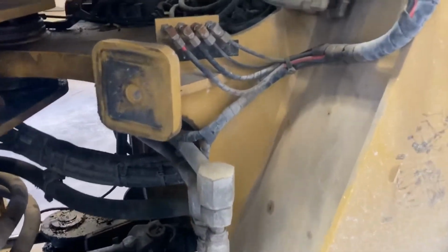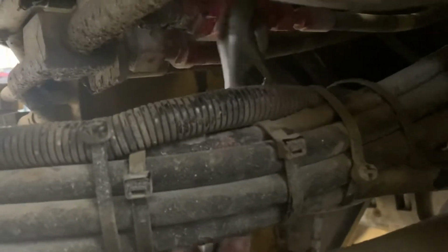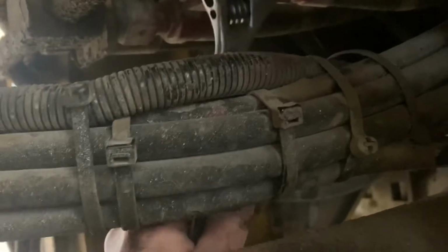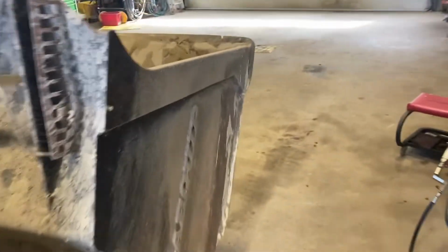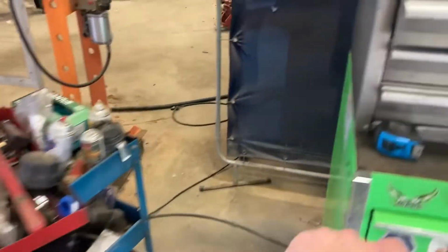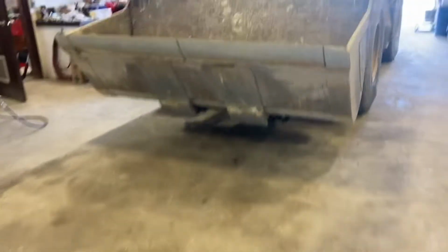If you wanted to keep it up in the air a little bit, you can always shut the valve back off again too. It's probably not a bad idea to exercise these valves. Like, it took quite a bit to get it to move there. Just to make sure, once in a while, just open it and close it when you're doing an oil change or something. So a crescent wrench works too, but a 3/8 goes right on there, or you could just buy a handle for the valve. Okay, so that's how you get it lowered.